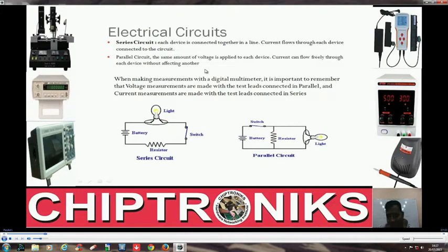How do you recognize that two resistors are connected in series, or that two capacitors are connected in parallel? If two resistances are connected in series, it means the same current will flow across both of the resistances. And when I say two resistors are connected in parallel, that means the same voltage is across both the resistances.